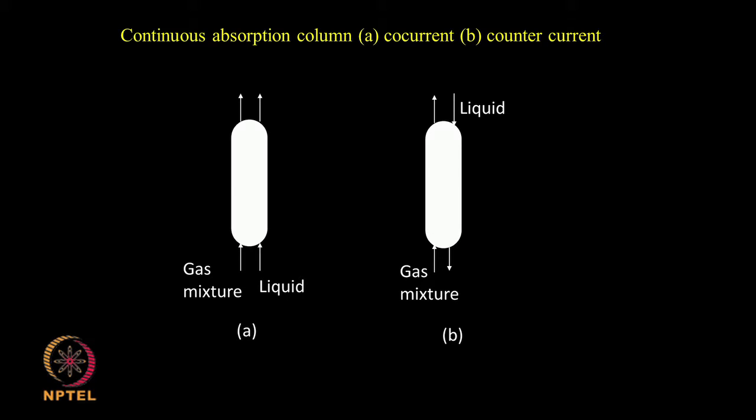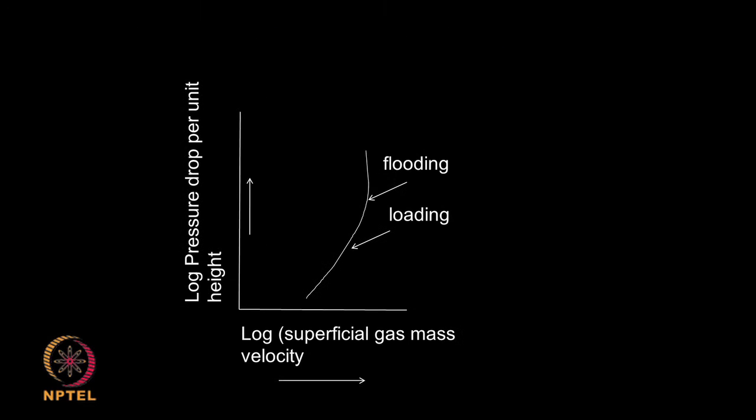Okay. So, this is a very useful technique because from an environmental and toxicity point of view, you would like to collect a gas leaving a fermenter; you do not want it to be vented out in the open. You can keep on increasing the flow rate of the gas, but you cannot do that too much. After some time the gas velocity will be so high that it will prevent the liquid from flowing down, and that is called flooding. Okay. These are very chemical engineering terminologies.